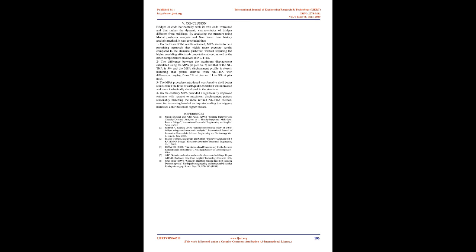2. The difference between the maximum displacement calculated using the MPA, at pier number 7, and that of the NLDHA is 5%, and the MPA displacement profile closely matches that derived from NLDHA, with differences ranging from 3% at pier number 11 to 9% at pier number 5. 3. The MPA procedure introduced was found to yield better results when the level of earthquake excitation was increased and more inelasticity developed in the structure. 4. MPA provided a significantly improved estimate with respect to the maximum displacement pattern, reasonably matching the more refined NLDHA method, even for increasing levels of earthquake loading that trigger increased contribution of higher modes.